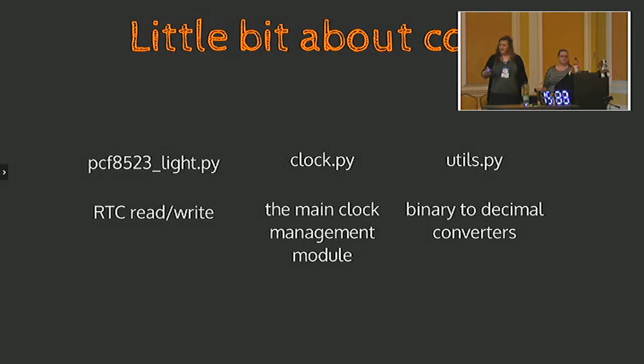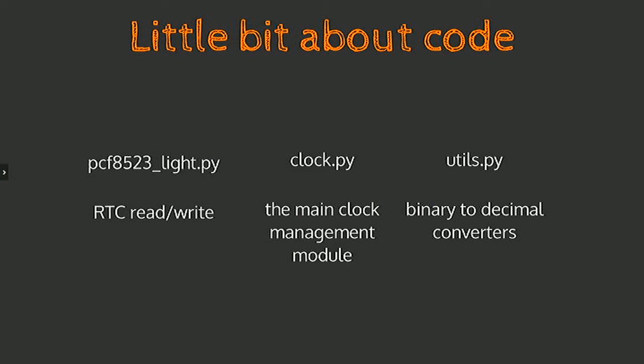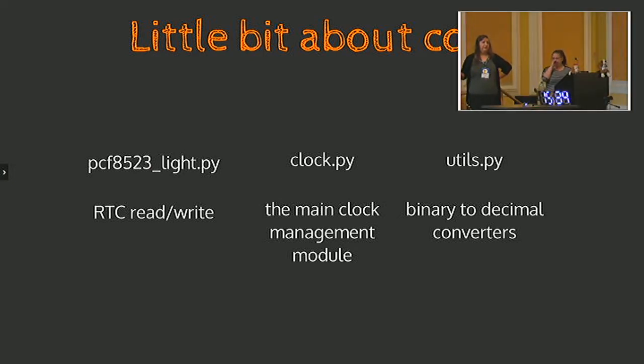Okay. So now let's talk a little bit about the code. For those of you who were in the talk before, I already mentioned Adafruit and said that they publish Python drivers, Python modules for all their hardware, and that's really nice. The problem we had with this clock is that there's a driver for the display, a driver for the RTC, and when you load both of them into the M0, you fill up the memory and you don't have any memory left to write your program.